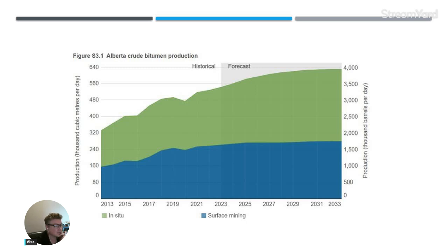Now, those facilities are not just oil and emulsion treating facilities. Those are also steam generating facilities, because remember, we established that we can't just mine with a shovel. We have to inject steam to reduce the viscosity of oil to be produced at the surface. But then we're constrained by the ability to generate that steam. To do that, you need more capex for steam generation capabilities, right?